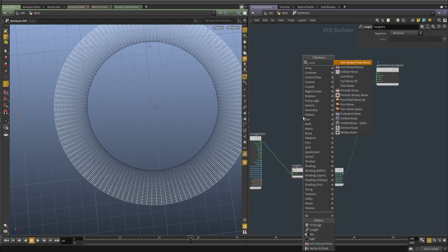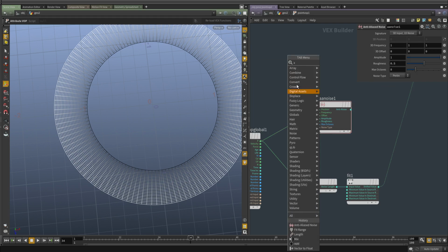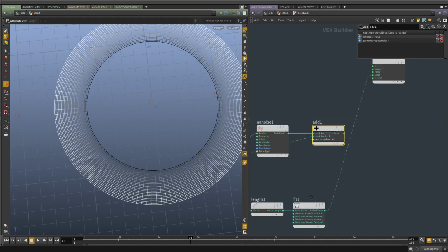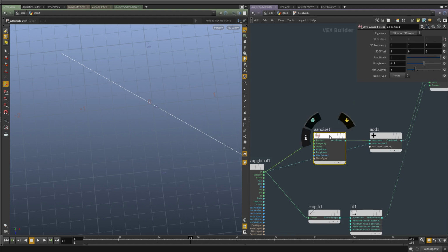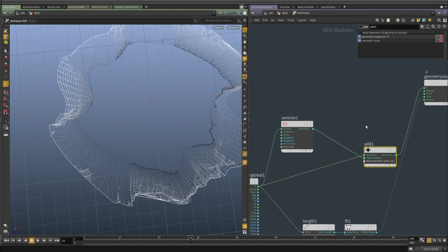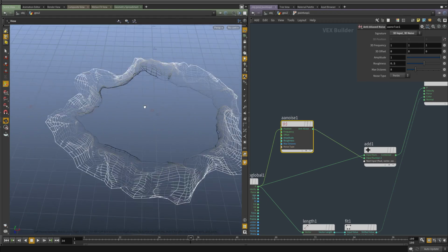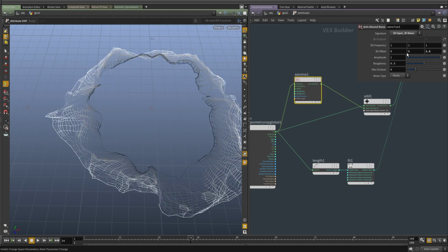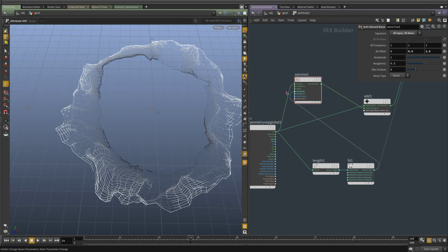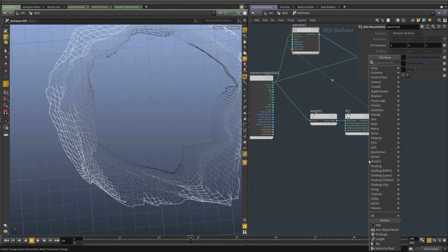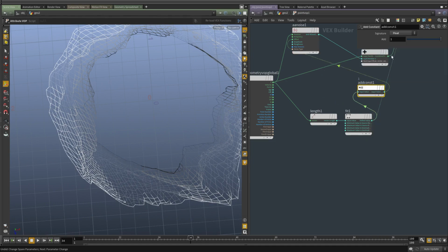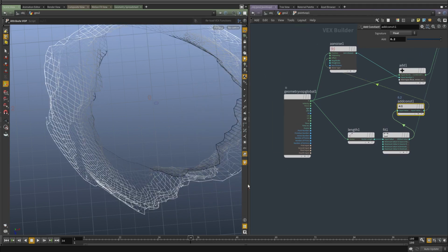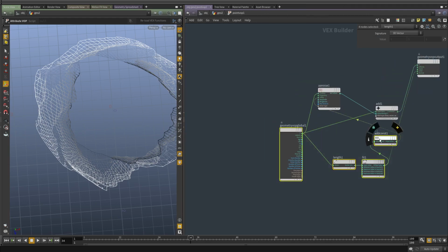So let's try the noise first. Let's add this noise here. Let's see the result. Okay, so right now it's a vector. So let's change it to a 3D noise, and let's plug this into the Z offset, or let's plug it into the offset as one value, the same offset for all of them. And let's use an add node. I'm going to use an add constant, so we have the controller here, and if we play, you can see it's moving along this path, but it's not behaving as we would have hoped for.